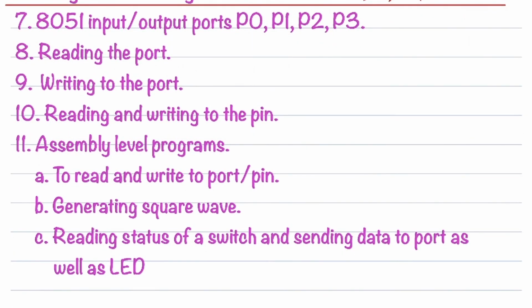In the 8051 input-output ports, we have studied in detail about port 0, port 1, port 2, and port 3. We have also seen that port 0 requires pull-up resistors, whereas the other ports do not. By default every port acts as an input port.